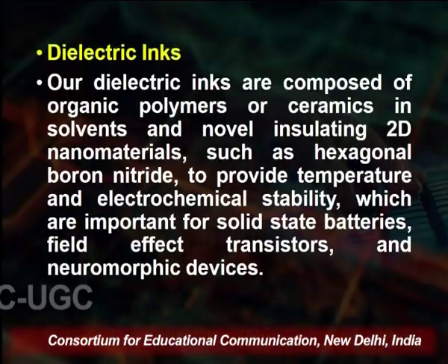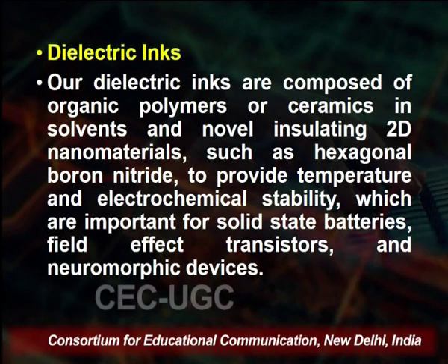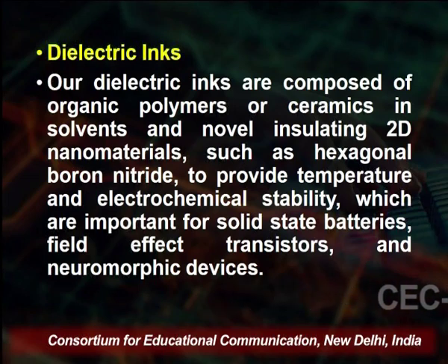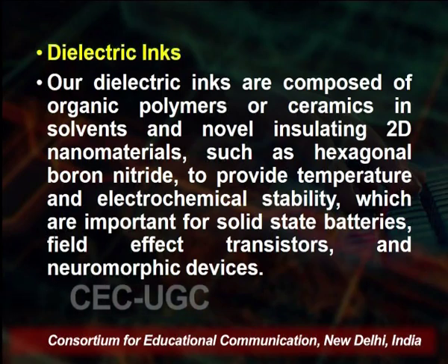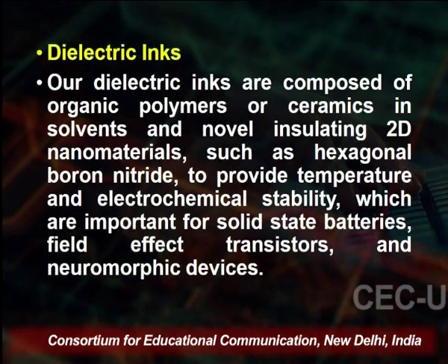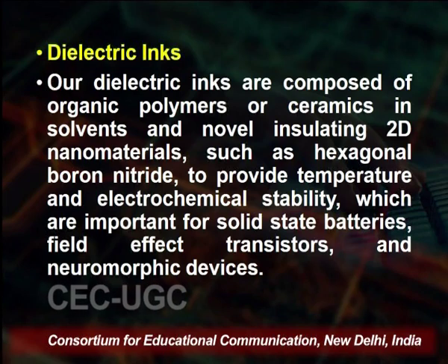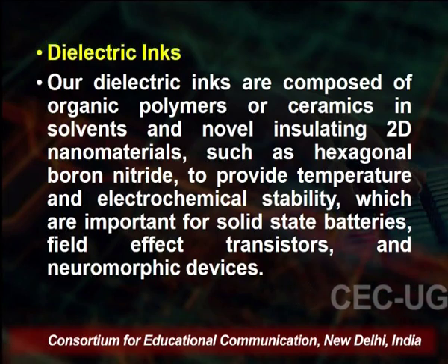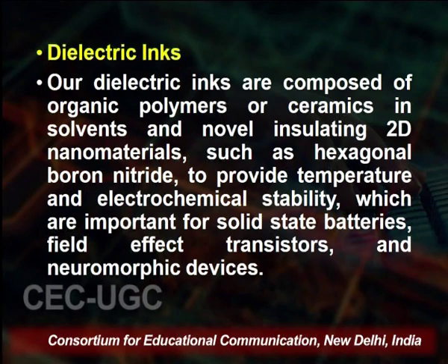Our dielectric inks are composed of organic polymers or the ceramic in the solvent. Means we take the solvent, then we have an organic polymer and ceramic that must be dissolved in the particular solvent. And the novel insulating 2D nanomaterials such as hexagonal boron nitride to provide the temperature and electrochemical stability, which are very important for the solid state batteries.